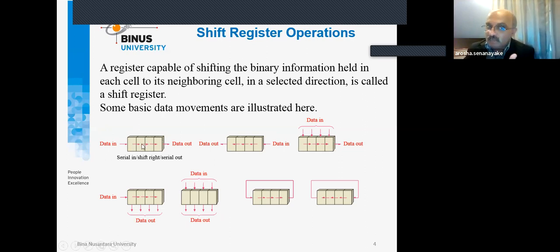And then if we again shift to the right, the second one and the first one will move along. And so forth, really 1 bit at a time, shift to the right, and the same way through the output cable you get the same sequence. So this is called shift right, and very important, serial in, serial out, 1 bit at a time.